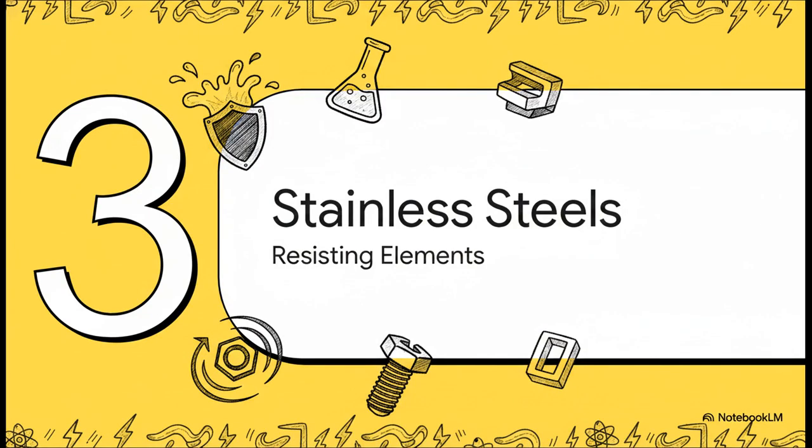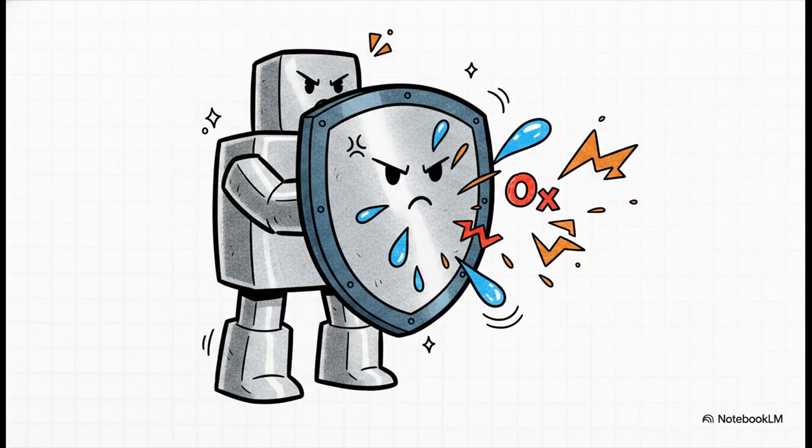Section 3. Stainless steels, resisting elements. So, remember that pesky corrosion problem we mentioned earlier? Well, let's explore a very specific branch of steel designed to solve exactly that. The absolute crucial point here is that adding at least 11% chromium to the mix is what gives stainless steel its legendary resistance to the elements. This chromium essentially acts as an invisible shield, preventing the underlying iron from ever reacting with oxygen and rusting. It's such a simple elemental addition, but it completely revolutionizes where and how we can use steel, especially out in the ambient atmosphere or in really severe chemical environments.